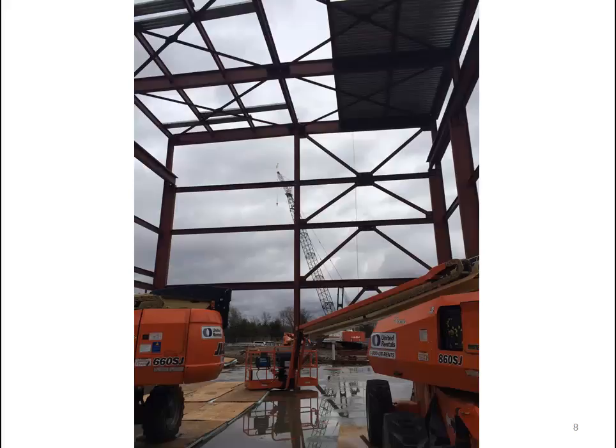And this structure is a little atypical as compared to some of the other photographs that we looked at, in that the size of the beam is smaller relative to the size of the column. And one reason for that in this photograph is we're really not going to have floor loads framing onto these beams. These beams are really intended to be axial members.